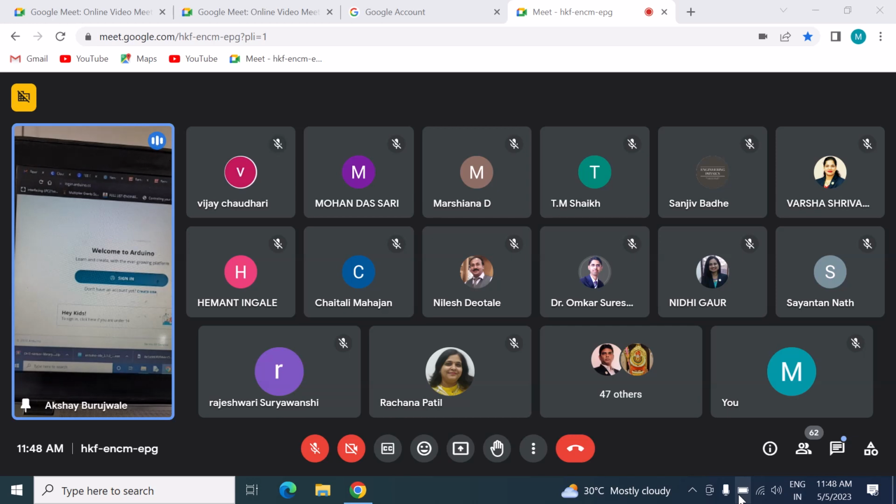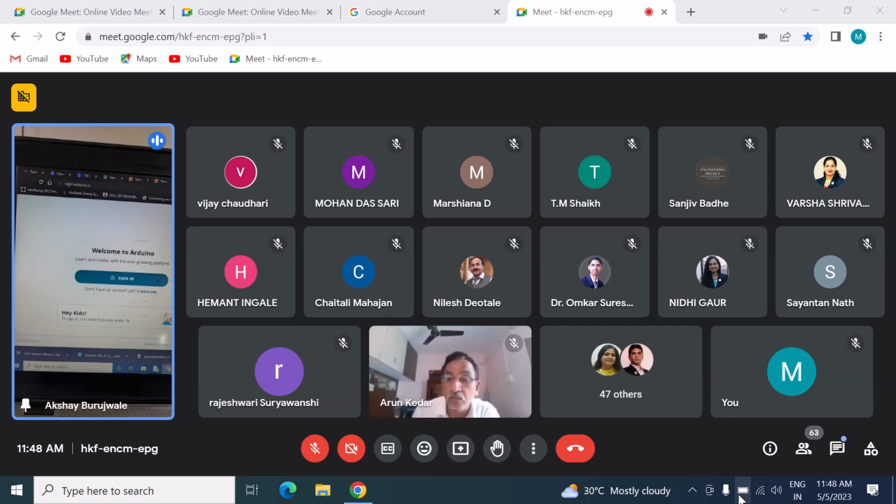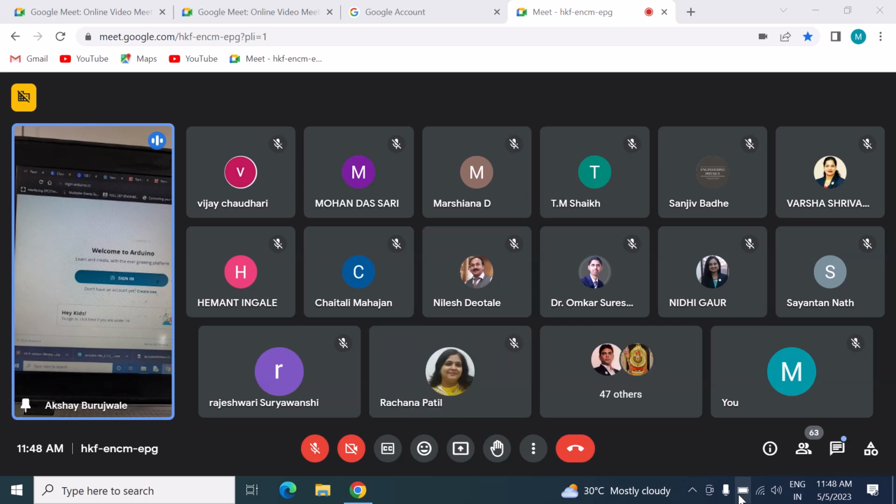So it depends on your device, what kind of application you have. If I want to make weather forecasting for a rural area, I have to go for LoRa because maybe there is no network availability. So I have to go for long range communication. Same if I'm using it for my company. A company has limited premises, maybe constructed, so that time I can use Zigbee. If I want to use it in my home, I can use Bluetooth or ESP8266. So depending on the communication distance, you can select your particular wireless module.